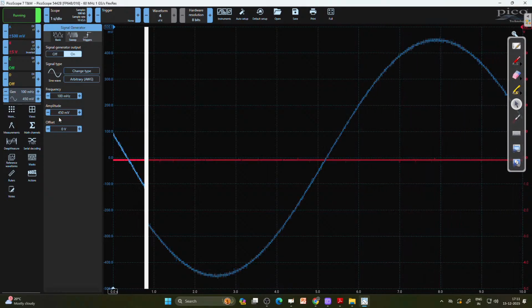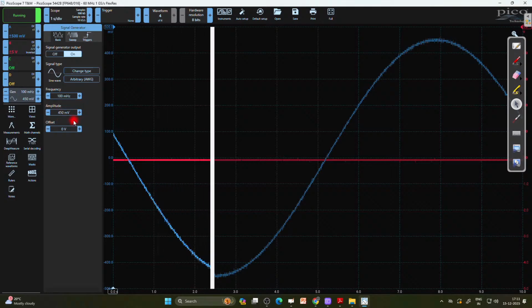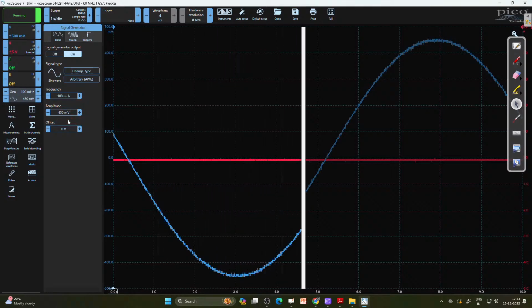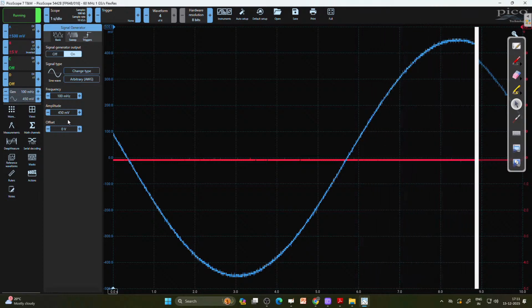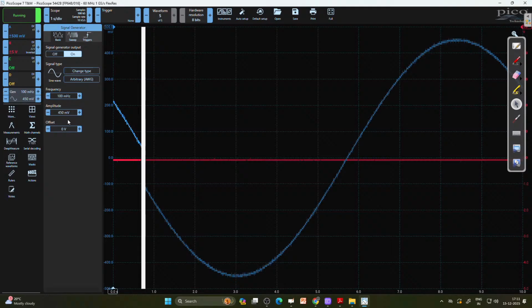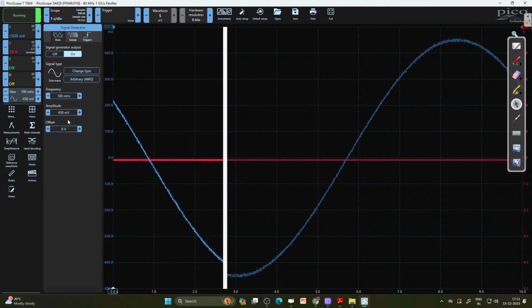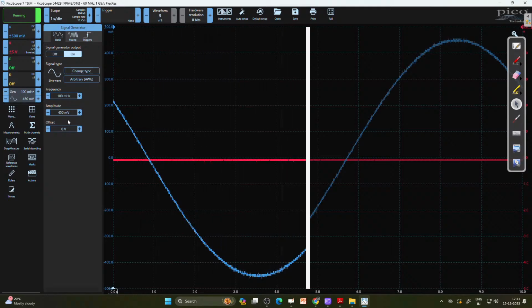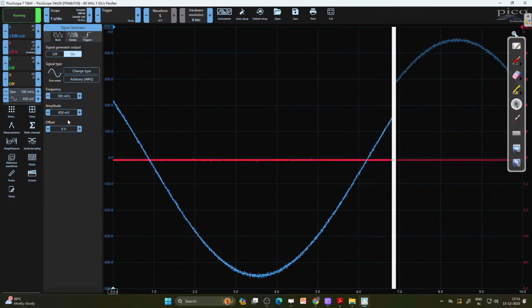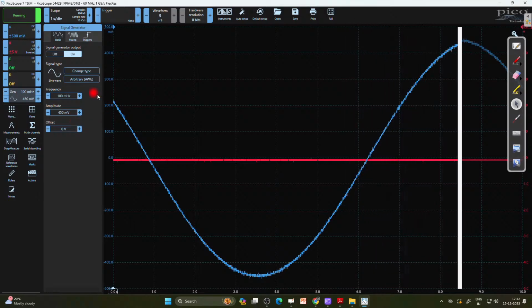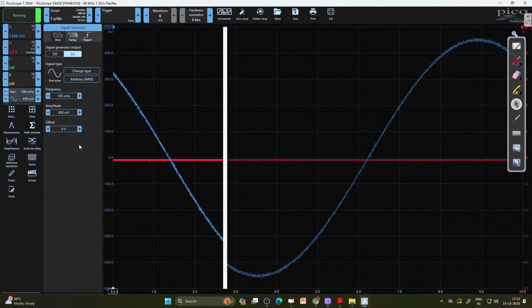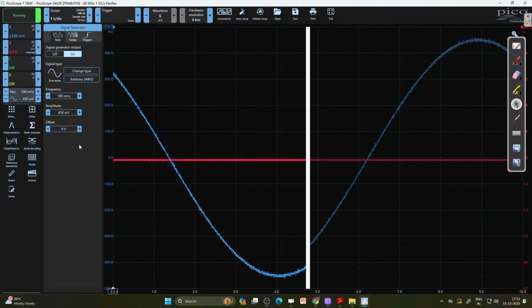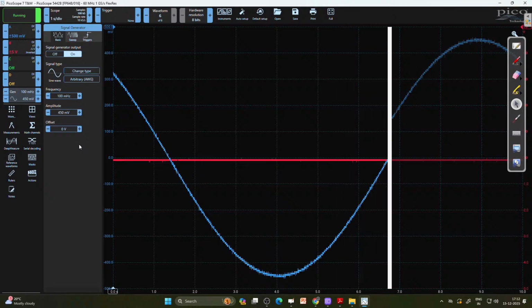So this is what you can now see, since I connected the signal generator output to the input channel A. You can see on channel A what the function generator outputs. And on channel B, you just see what the laser distance measures. Nothing. That is good. But this voltage is far too low to drive the piezoceramic stack. It's just the control signal we put into the high voltage amplifier.